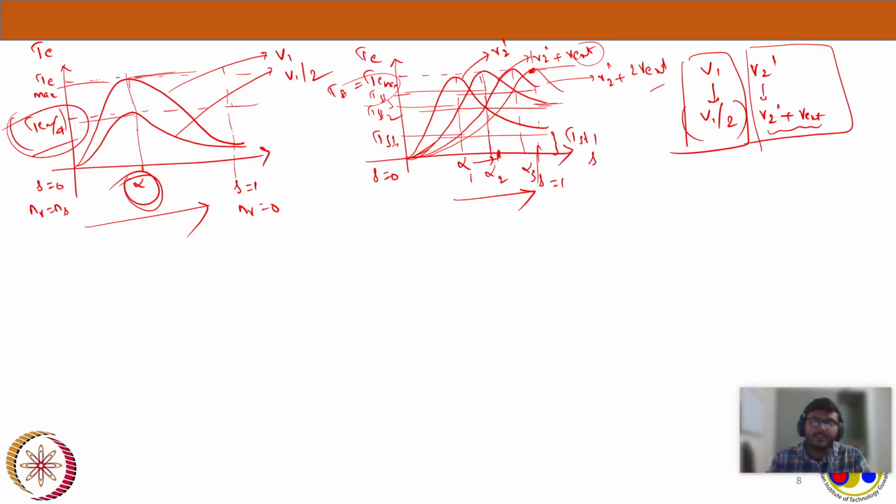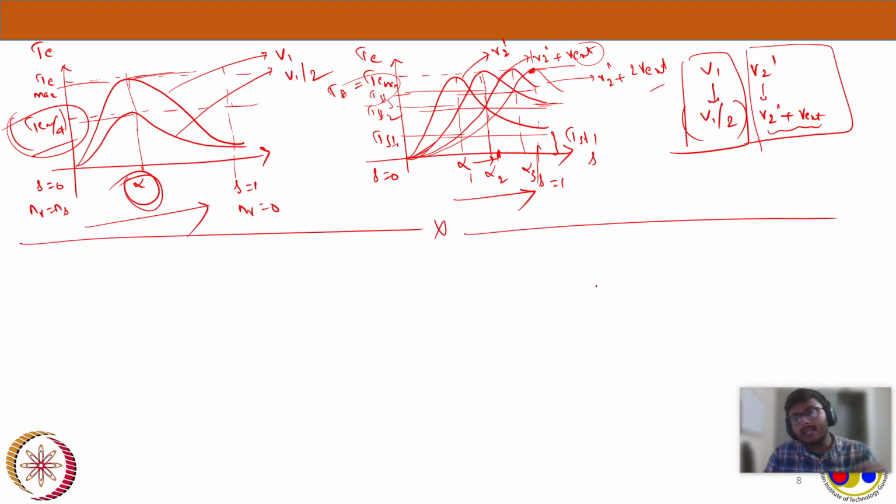But the slip at which the maximum torque occurs will change, because my slip will directly be affected by the rotor resistance, because the slip formula at which the maximum torque occurs is S equals R2 dash divided by RTH plus under root that one. So you will get a difference with that. That's what you have to observe here. So with that, this discussion on the equivalent circuit of a three-phase induction motor ends here.